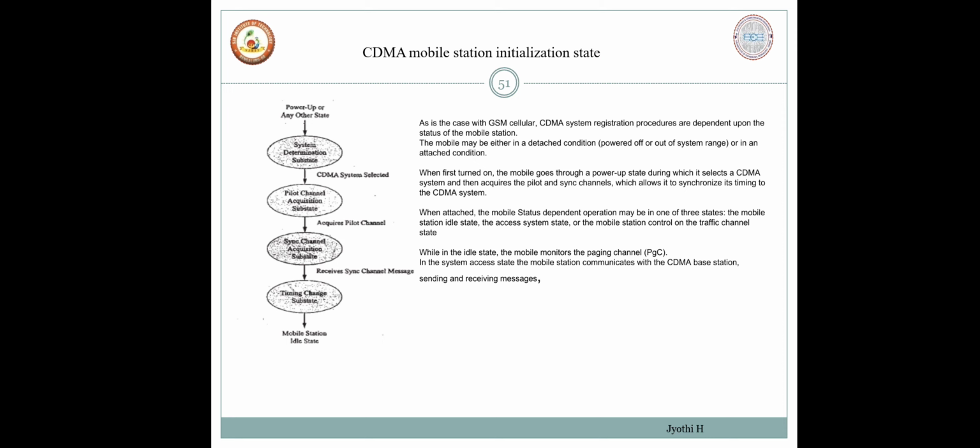You are able to see that when it is powered up, it is connected to the system, which creates the CDMA system selection, then the pilot channel is created, then the synchronization channels are created, and the timing for the call. This is the procedure required from power up to the mobile station in idle state.